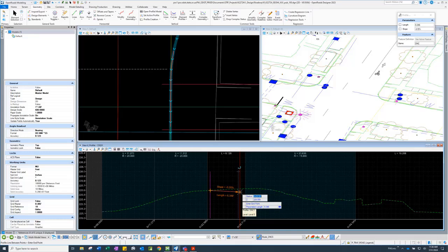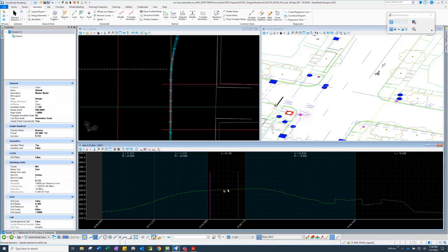Okay, so just wanted to verify that you're in the vertical group on your geometry bar, and you have been while you've been working on the profile. Okay. Correct. Yep. And I can turn off Civil. I can draw. So the next step, I want to place a line from here over that is at 1.5%.